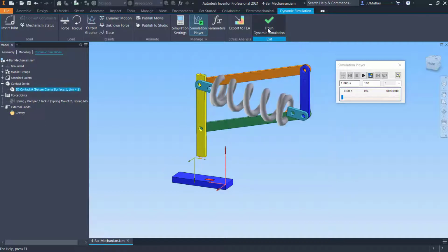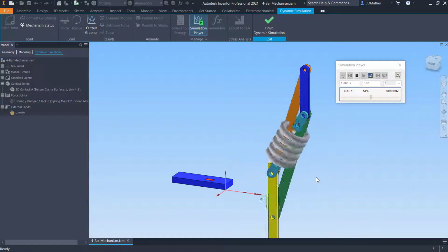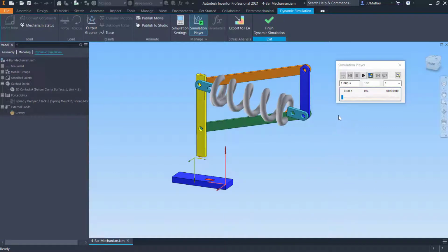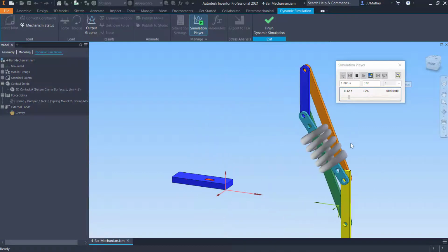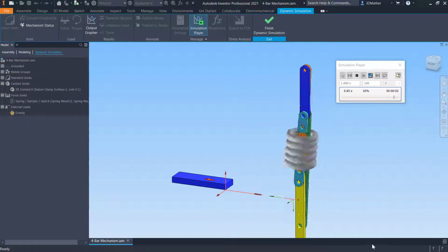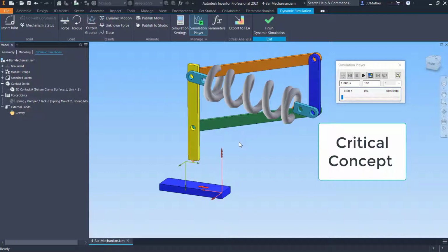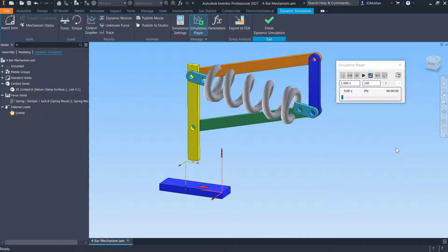And then if we go to the properties, we could change this restitution and friction, let's say maybe 0.5 on this. Play this again, and it went right through, but notice when it came back it hit against this and stopped. Let's do that again. So it went right through, watch it comes back. It hit it, and then it went back that direction. So here's what's happening. At the precise point where this came down here, where it would have contacted that, it wasn't doing a calculation. So we need to do more calculations.